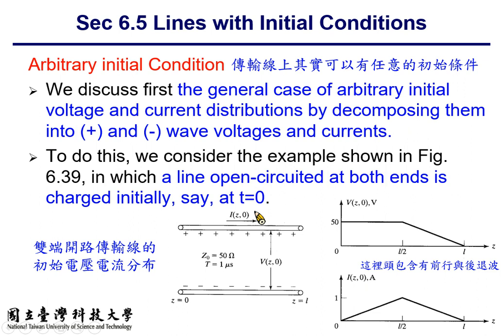Short and open circuits do not absorb energy, they just reflect the energy. Inductors and capacitors may store some energy. However, they do not dissipate energy, do not consume energy. So only resistive loads, resistors, will consume energy.